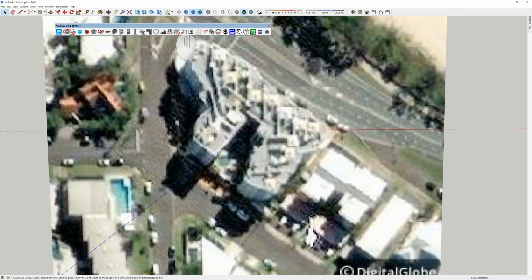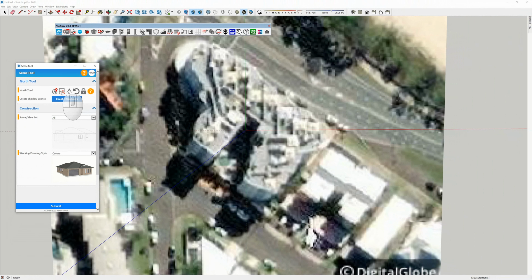So what I'm going to do is I'm going to go back to my tool now, and I'm going to go in here and I'm going to click on this first one, which is basically we're going to choose a location to set a square point from so our axes line up. So I'm going to zoom into here, and as you can see it is low resolution, so it is harder. And then by default PlusSpec or Plus Design Build lined up our axes, so I could actually go and say, right, well I want my axes to line up with here. Right, so now I'm 90 degrees, and then when I draw a rectangle or a wall or anything like that, I can actually start to draw on the axis of the model.